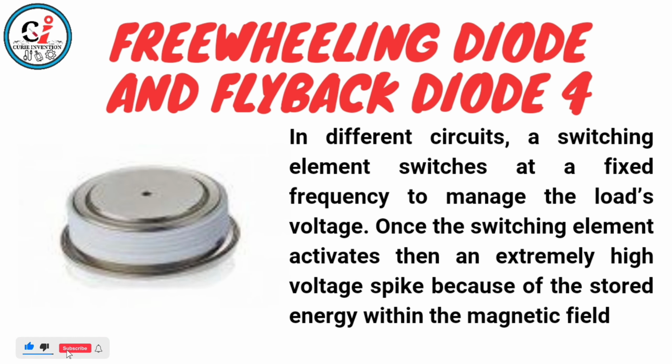Freewheeling diode and flyback diode. In different circuits, a switching element switches at a fixed frequency to manage the load's voltage. Once the switching element activates, an extremely high voltage spike occurs because of the energy stored within the magnetic field.